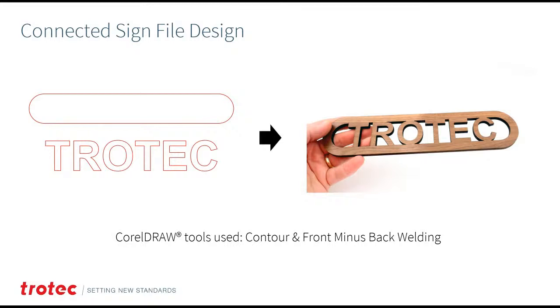All right. Moving forward here, here's a simple connected sign file design. So we're going to use the contour and then the welding tools, the front minus back welding tools, to show you how to connect signs and graphics and stuff like that. And so that you can take just simple text and a simple outline, connect it together to create dimensional, three-dimensional type signage or graphics or components of some sort.